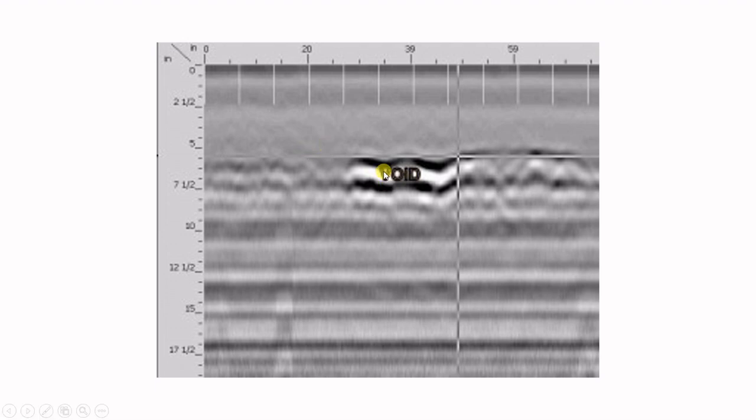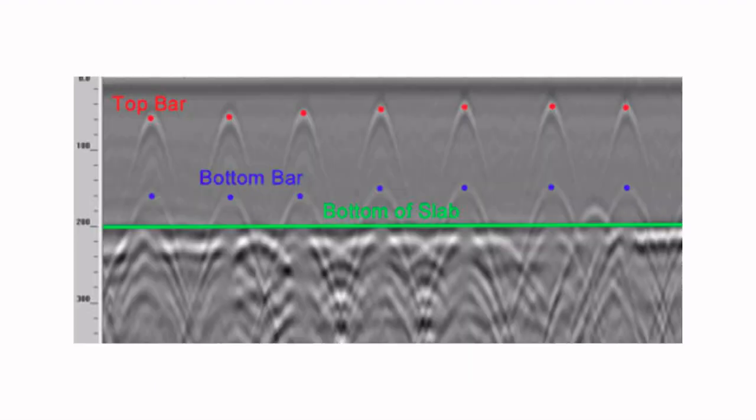And when it comes to void space, if you have any void, then in the long term it will damage this particular part. It can be on the road or on any slab or a pillar or anything. To fill this void, we need to identify it. So instead of breaking it, we do the GPR scan and then we find the void, and in that particular location we do the correction. This is how we can use the GPR.